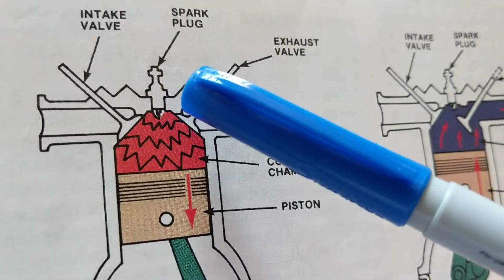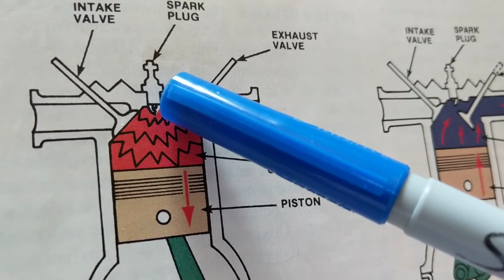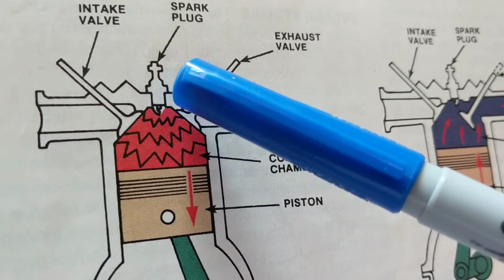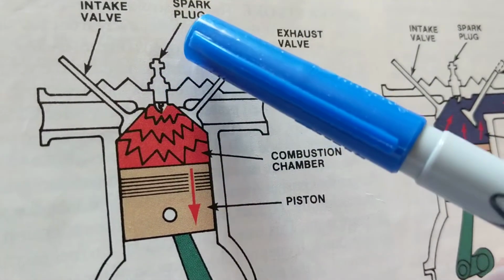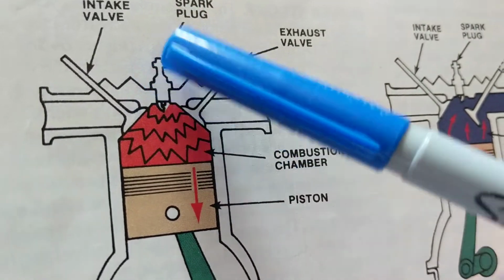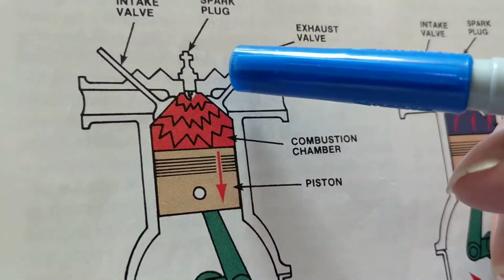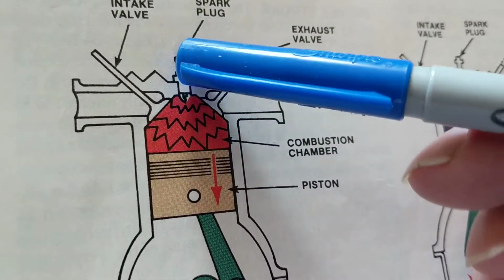There's a transistor in there, we spoke about that. The transistor goes to the ignition coil, called a transformer, cuts it on and off, a collapsing field, and then creates a spark. That spark comes in here. Where does it go to? Through the spark plug wires. Goes over here, right over here in the cylinder.